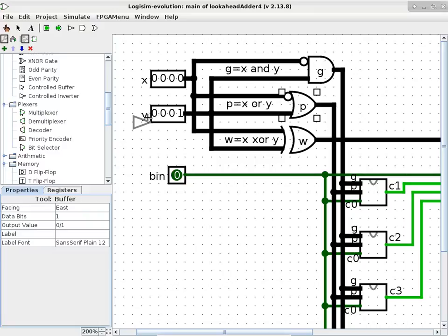the signal. Because I think in LogicSim, the way it does the simulation is it relies on the dependency not getting into oscillation. So it's basically going with whatever is changing first, and then it propagates all those changes, and then it will say, okay, are we done? If any one of those things can go back and change the state of any component at the same time, then it will report back and say we have an oscillation, but it won't actually simulate the oscillation itself. So it will detect it, but it cannot simulate it.